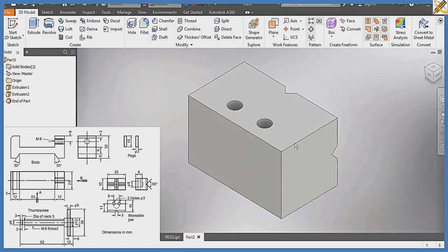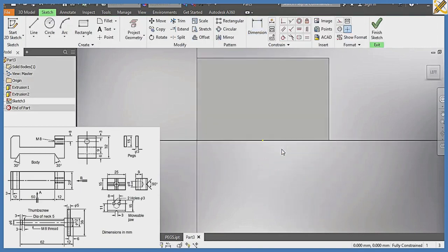So then turning to the back here, clicking on this surface, you create a sketch. We are having a hole there. All right, that hole is a hole of diameter 8 as seen on the end view. Diameter 8. All right, hole of diameter 8, and that hole is sitting at the middle. So picking my circle, locating the midpoint here, coming down to the midpoint here also. Okay, I think this is the midpoint here. Diameter of 8. Enter.